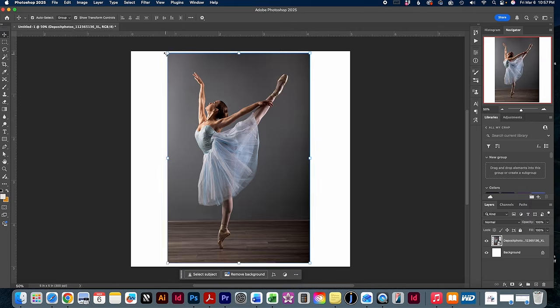Now if you don't see these squares, you can come up to the control bar here and click Show Transform Tools. So your screen might look like this, and if you click it, they'll appear. There's also auto select over here. You can auto select group or layers. I usually leave it on layer.